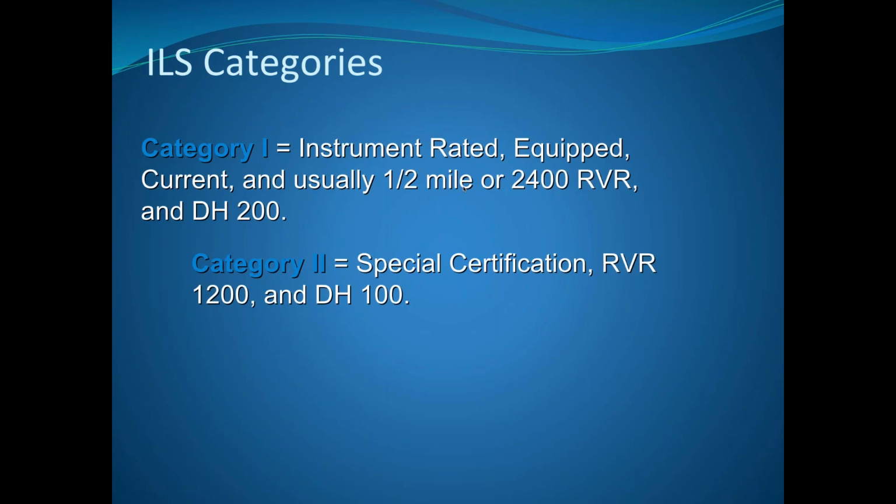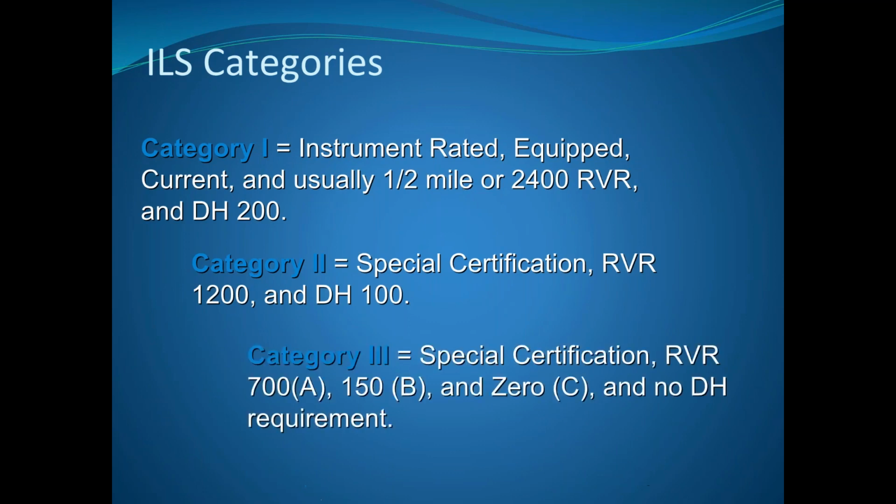So yeah, the important thing to remember about category 2 is that it requires that special certification, and not just anybody. It has to be in your op specs that you're allowed to operate and do category 2 minimums on your approach. Category 3. So this is